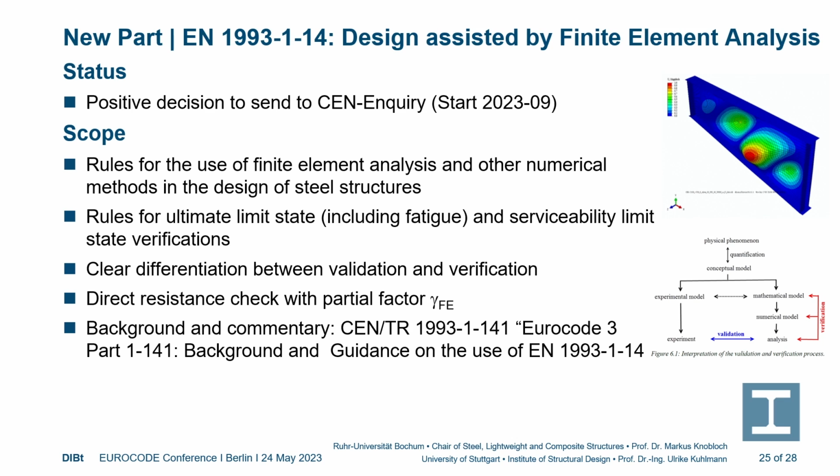Let's come to our new part 1.14, design assisted by finite element analysis. And in fact, this is not completely new. We have had as a core element the Annex C of part 1.5 and also the rules in part 1.6 for shell elements. But we decided to have this now valid for all applications, giving rules for the use of finite element analysis and other numerical methods in the design of steel structures for ultimate limit state, including fatigue, and serviceability limit state.